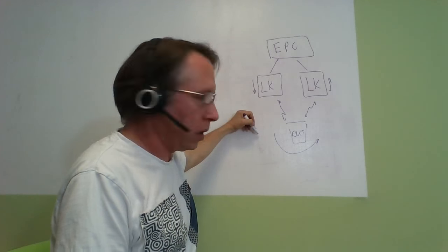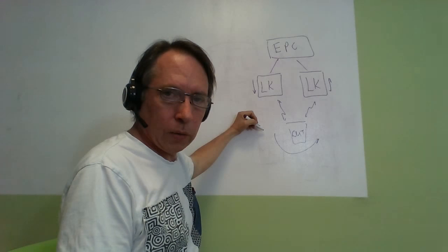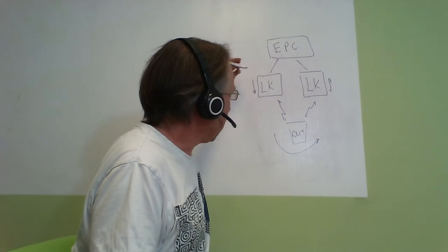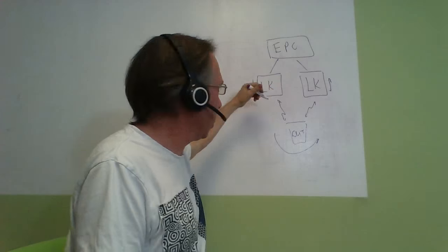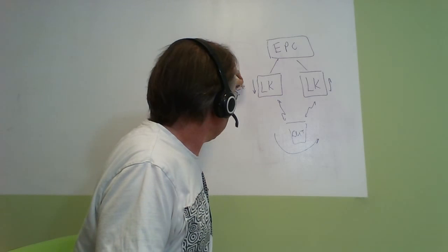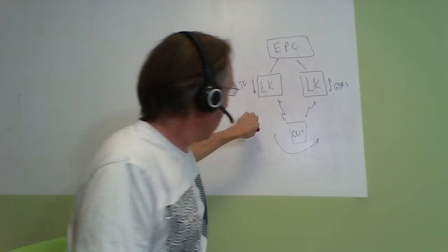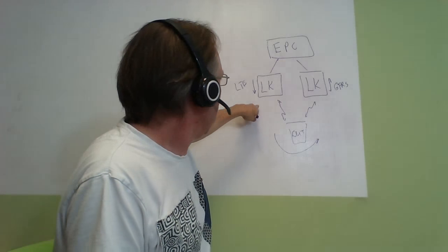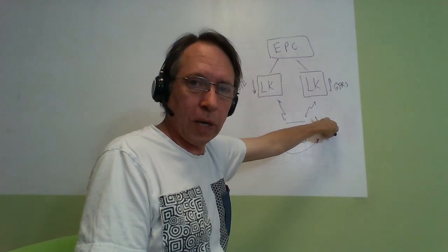And by doing this, you can induce mobility and handover behaviors, and then see how your device under test is going to behave. Because in the simple, obvious case, these are both just normal LTE cells that are attached to the same network, but they don't have to be. So, for example, one could be LTE and one could be GSM GPRS. And what this does is it simulates what happens when your device under test moves from an LTE network into an area that doesn't have LTE coverage and has to fall back to a 2G network.